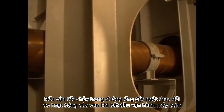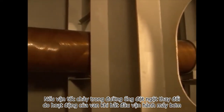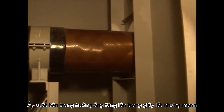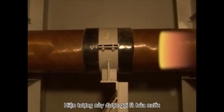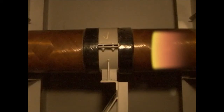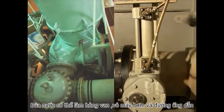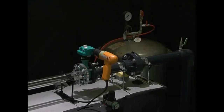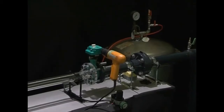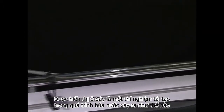If flow velocity within the pipeline suddenly changes due to valve operation at the start of or during pump operation, the pipeline internal pressure increases momentarily but sharply. This phenomenon is called water hammering. Water hammer can damage the pump casing, valves and pipeline. Shown here is an experiment reproducing the process of how water hammer occurs.